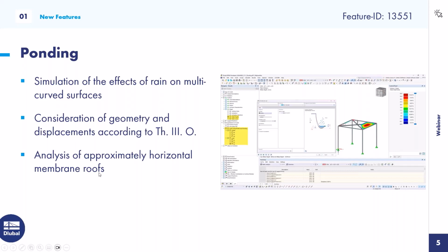So as I already told you, the more horizontal a membrane is, the higher the effect, depending on the pre-stress amount you put inside the geometry, and this may affect our results. Because we of course also want you to be able to evaluate the results you receive by the load, you will see soon in the program, once I show you the example, that you will get two new entries, the water depth and the water level, inside the shape surface result tab.